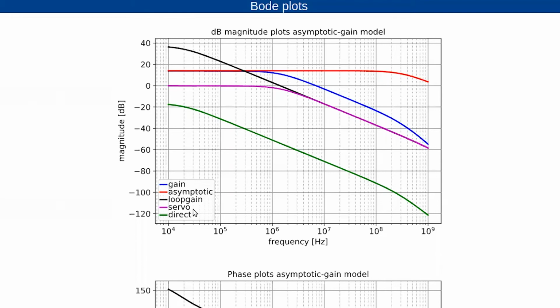And you see the asymptotic gain is not a straight line. And if you would calculate the value, this low frequency value would equal the ideal gain. But at high frequencies, there's attenuation because of this capacitor. Well, at low frequencies it would also be a little bit less because of DC attenuation, because of the input resistance that was also there.